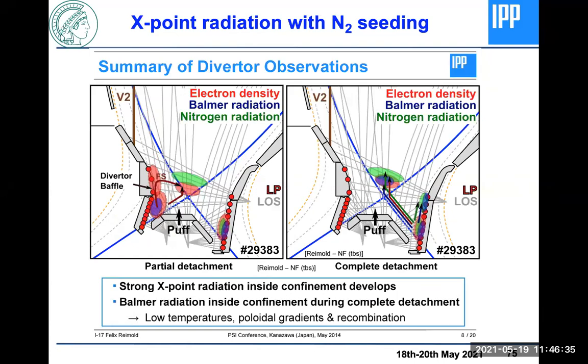So you look at specific nitrogen lines, wavelengths that are characteristic for nitrogen, where you don't expect any other impurity or any other molecule to interfere, so that you're sure you're looking at nitrogen and not fluorine or oxygen or tungsten. You need to be sure the wavelength is well chosen. Otherwise, if your spectrometer doesn't have a high enough resolution or you selected the wrong wavelength, then you may have two neighboring lines of two different species, and you may be looking at the wrong thing. So that's why you need to be careful.